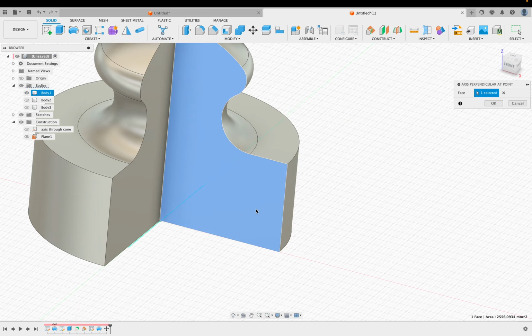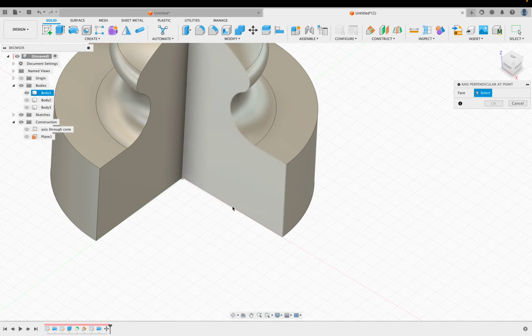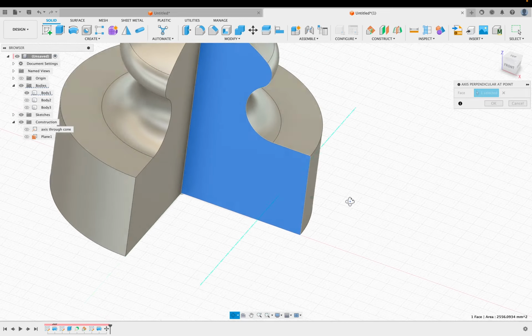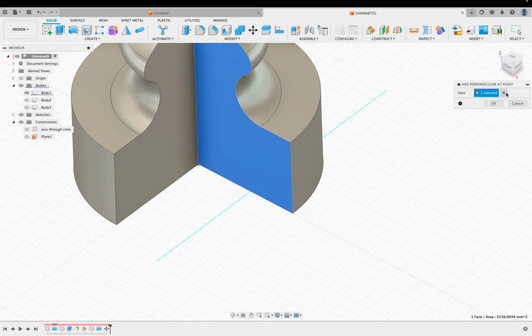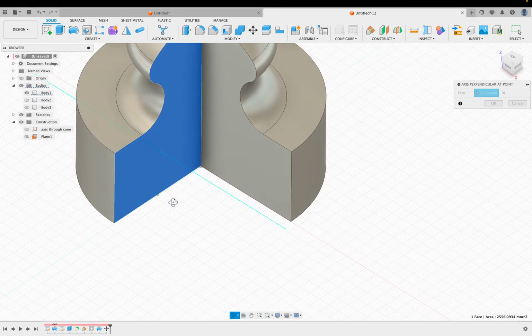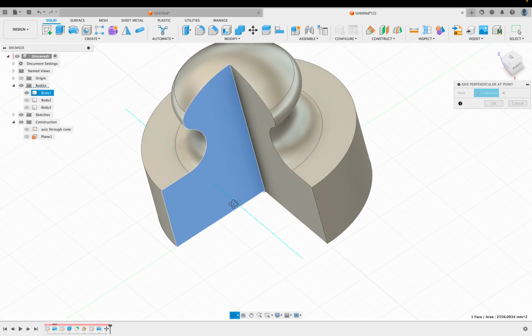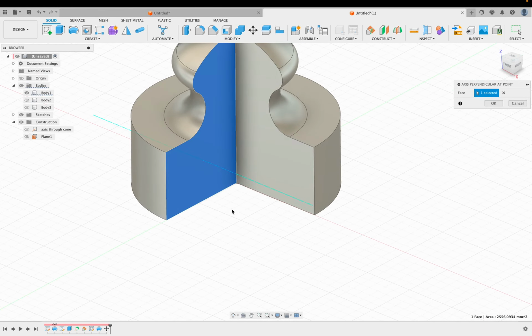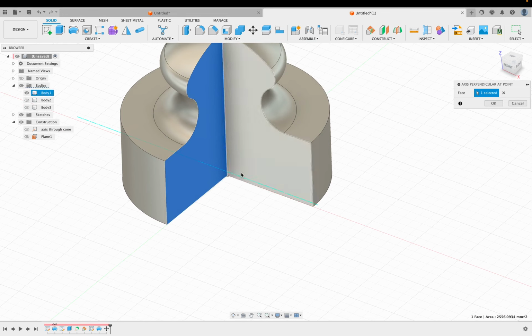Let's click another point. You see an axis was created right there. Let's select another point. You can see that this is creating an axis at the place that I'm clicking. Okay, let's click the other face. So it doesn't actually have a dimension. It's not something that I dimension, but it's something that I put on a face without the dimension. Now, this can be useful when creating other features that depend on this axis. For example, creating a plane at an angle.